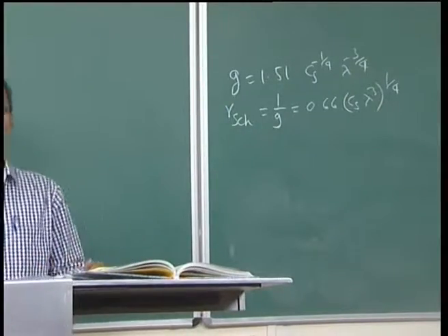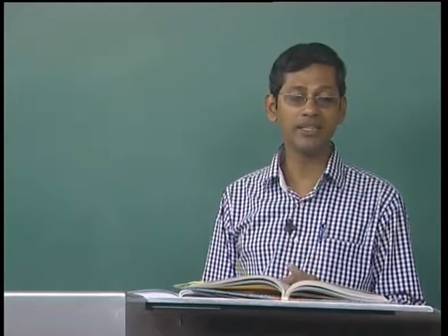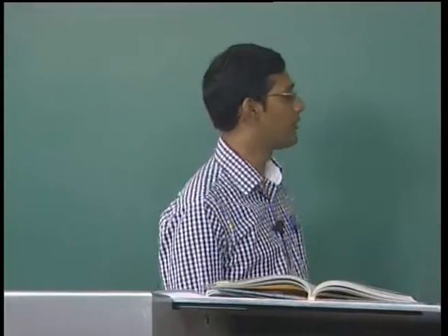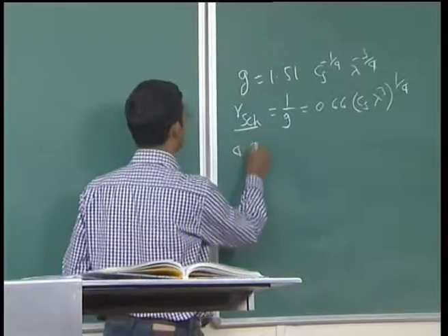In fact, there are reports that in the 1970s a detail of 0.66 Angstrom was achieved, when the interpreted resolution was about 3.3 Angstrom. So, you can see that seeing detail in an image does not mean that you can gain any useful information about the microstructure. There is a distinct difference between the resolution limit and the information limit as far as the microscope is concerned.